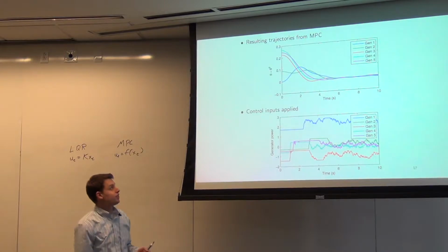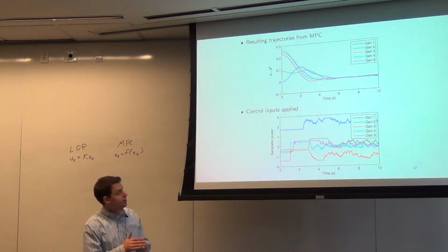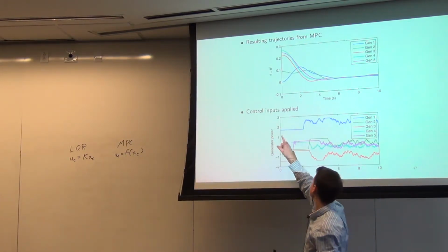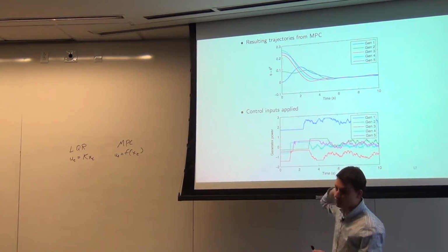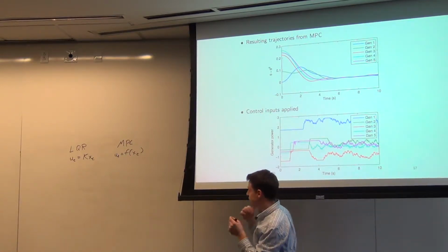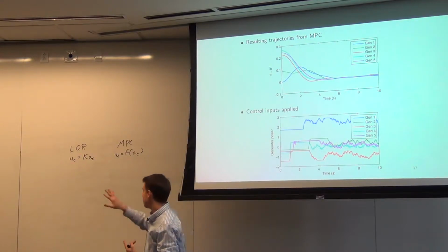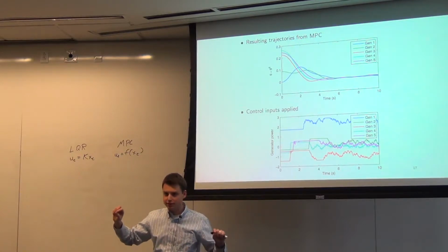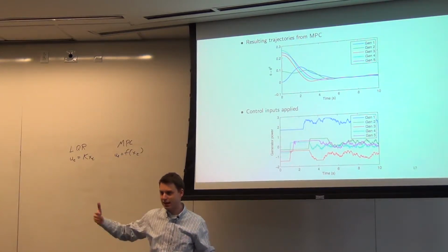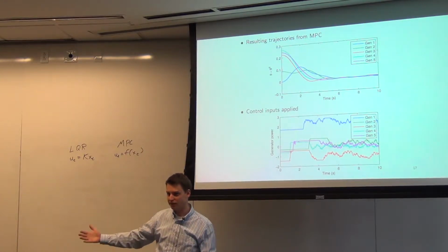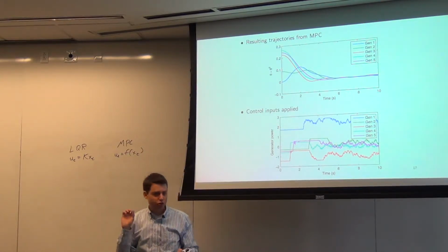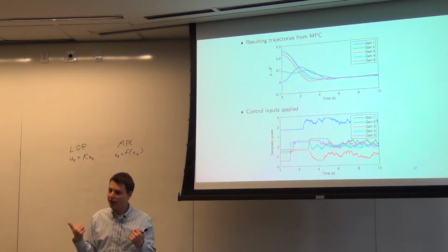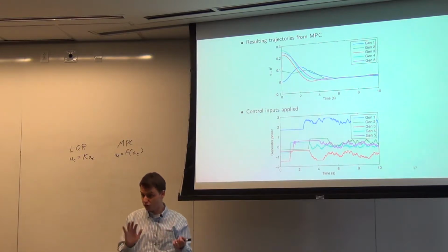So here's what happens with MPC. What you'll see is that, as you did with LQR, you have a policy that roughly controls the system to its desired point. Now, remember, LQR and MPC, for the stochastic case, both these things are never going to exactly get the system to its desired state, right? Because even if you're at its 0 state, the next time you won't be because there's some random noise you couldn't have possibly predicted. Okay, so we're throwing out the hope of ever getting the system exactly to 0. I mean, you can get it pretty close by having really big control actions, but typically there is going to be a trade-off between control and generation.